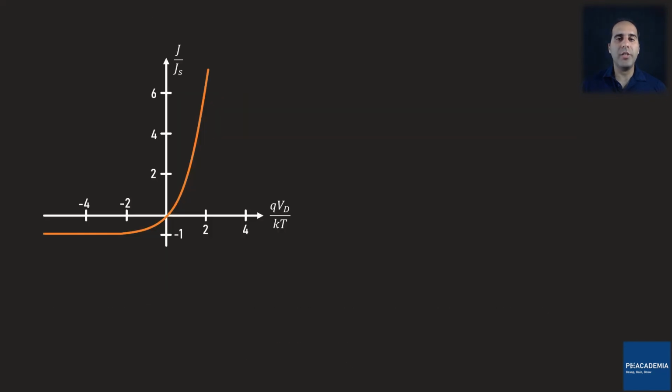You already saw this normalized current density voltage diagram for the PN junction in the previous lectures. What I did not show in this diagram was the avalanche breakdown. If I increase the reverse voltage applied to the PN junction diode, I get to a voltage at which the reverse current skyrockets. This voltage level is the breakdown voltage V sub B.